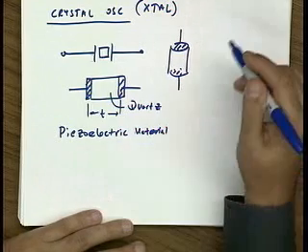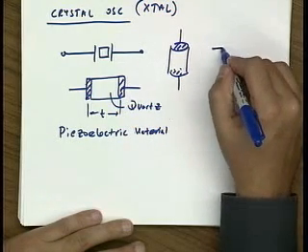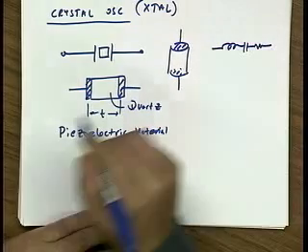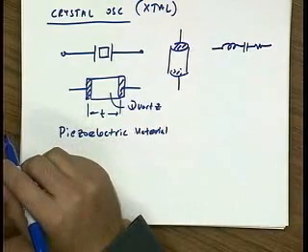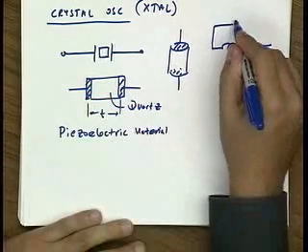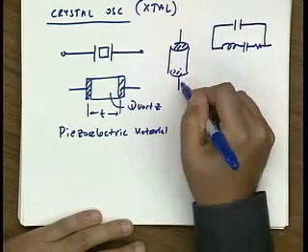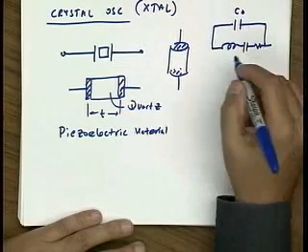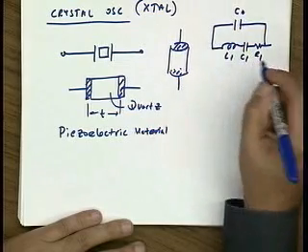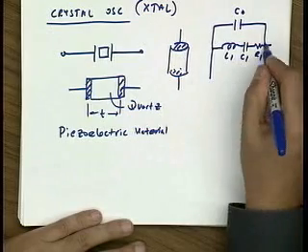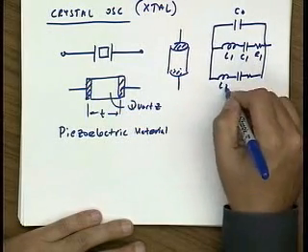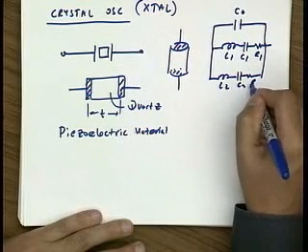The equivalent circuit for it looks like this. You basically can model each resonant mode with a series LCR circuit. There is a physical capacitor, which is just basically this parallel plate capacitor. Let's call this C0. We can call this L1, C1, R1. And because it has multiple modes of resonance, basically the harmonics, you have to model those as well.